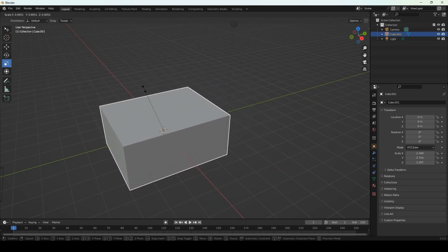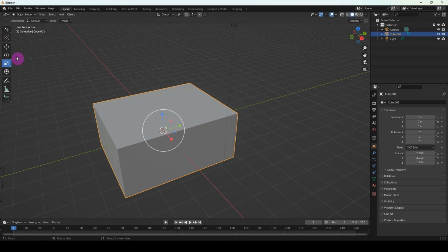All right. Now the shortcut keys, if you do forget, if you were to left click on the edge of any of these tools, hold on your left click and drag out, like so, you can see the names of the tools. Also, if you hover over any of the tools, you would see a description of that tool, and at the end you would see the shortcut key for that tool. All right, so for this one we can see that it's the G key, and if I hover over the rotate, we can see that it's R, and the scale is the S.